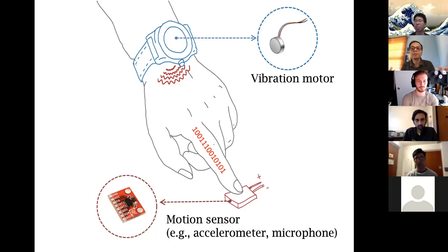Now what will happen? The magnetic mass is going to move in some weird ways, depending on how the signal is going back and forth. Now you receive that signal at your accelerometer. That signal is how the vibration happened, which is again a function of what signal you gave into the coil. So now you have the accelerometer signal, and you take an FFT again.